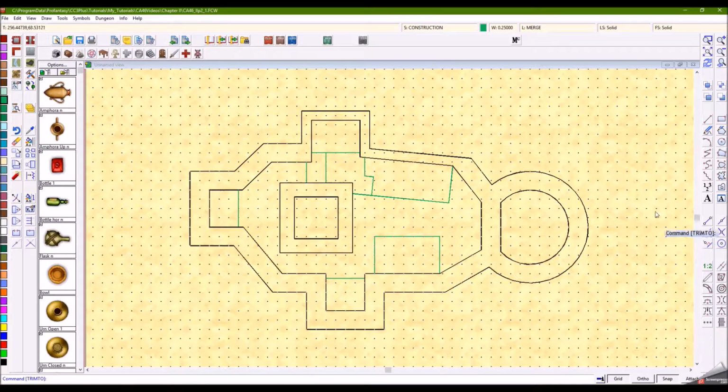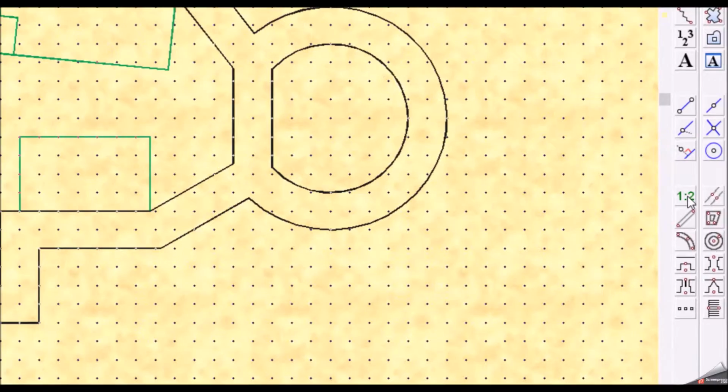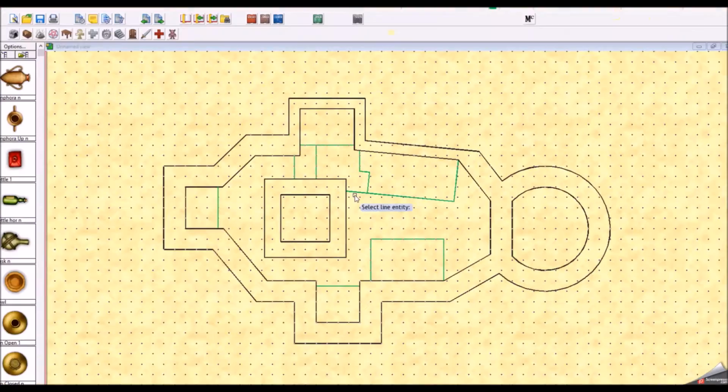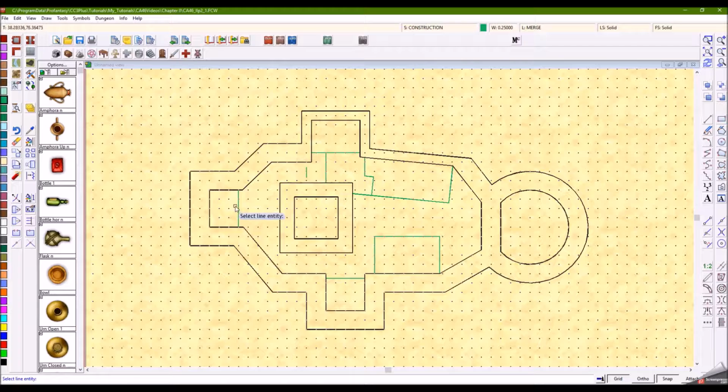In part 1 of chapter 2, we already saw that the double line tool doesn't respond very well to connecting construction lines. The solution is to use the half scaling button to reduce every construction line so that the endpoints don't meet anymore, and that way we can use the intersection modifier to still get the points we need.